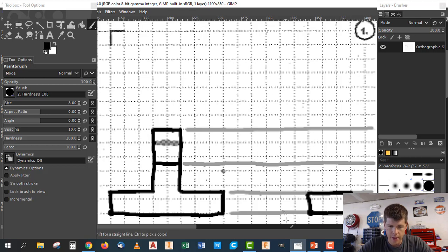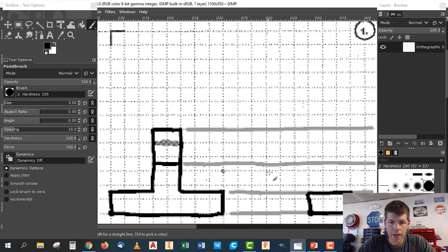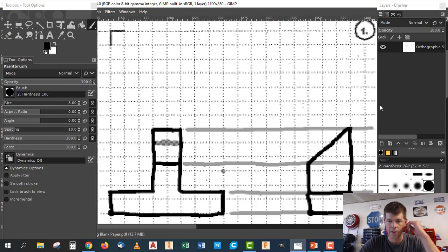And then I know this thing is angled. So if I look at this, we're looking at it from this direction now. The left side's going to go up a little bit, the right side's going to go up a lot, and then there's an angled line that connects them. So the easiest thing to do is find the sides first, and then the angled line will work itself out. The nice thing is the height of these has already been determined. We're going to go to here and up to here. So I can go straight down, connect, straight down, connect, and again, these are supposed to be straight lines. So connect your endpoints. There we go. Okay, so there's my right side view.